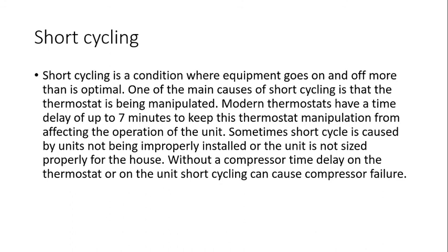There's also when the unit is not properly installed or they're mismatched, the size of the outside to the inside. That is also a problem that needs to be corrected. And some people get a really good deal on something that's not right, and they put it in their home and it just stops working properly. There are a lot of things that can be done to check for this, but usually short cycling stops a compressor from working.